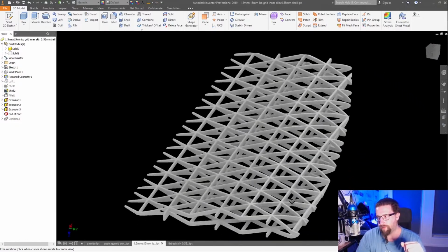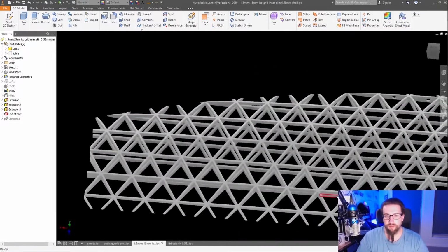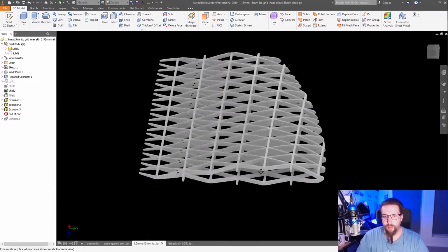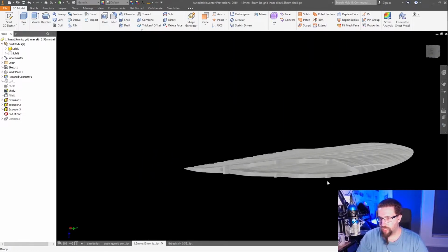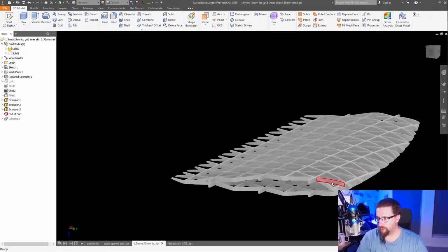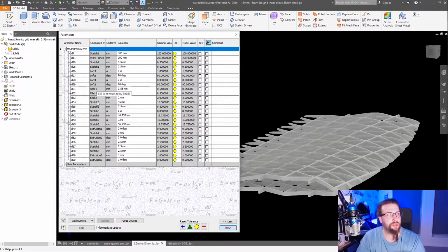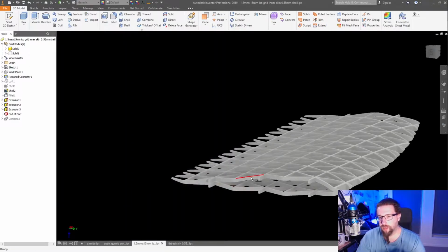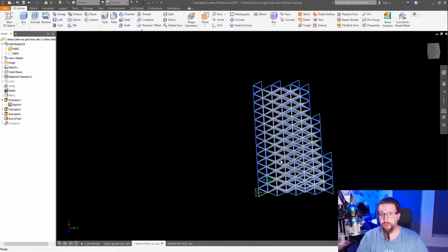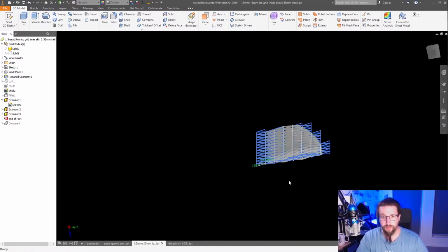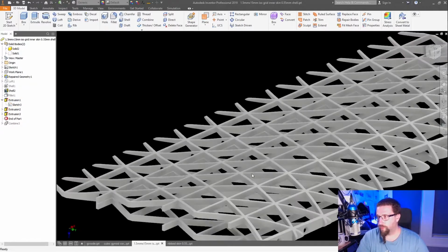So next up, I've designed this, and you'll probably recognize it. This is an Isogrid. Basically I created a 2mm shell of the wing. I duplicated the solid block, the original blank. I duplicated one of them. I shelled one to 0.55 millimeters, and the other I shelled to 2 millimeters. So this is a 2 millimeter shell that I then created a triangular pattern, a grid, and just extruded them through the 2 millimeter shell. And that left me with an Isogrid.